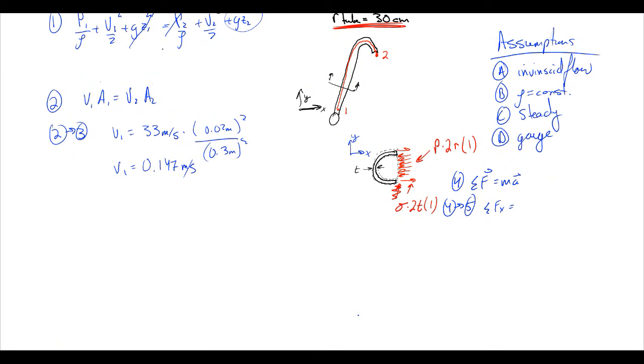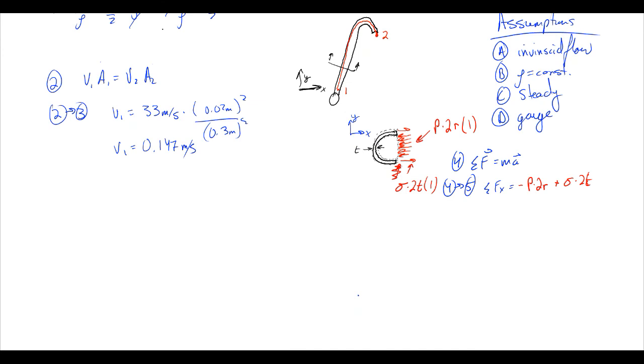Great. So we know our thickness of our pipe. We know our yield strength of our pipe. We know our radius of our pipe. So we know everything in this equation except for our pressure, and we can solve for it because this is stationary, so it's equal to 0. So we got 5 to 6.